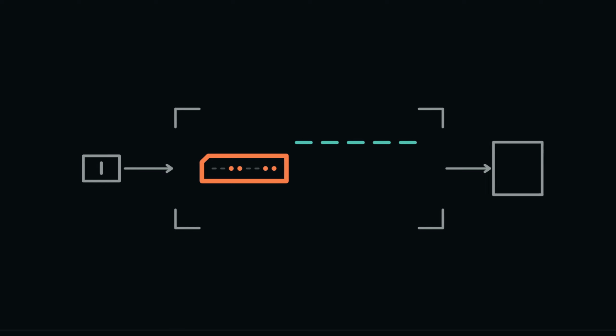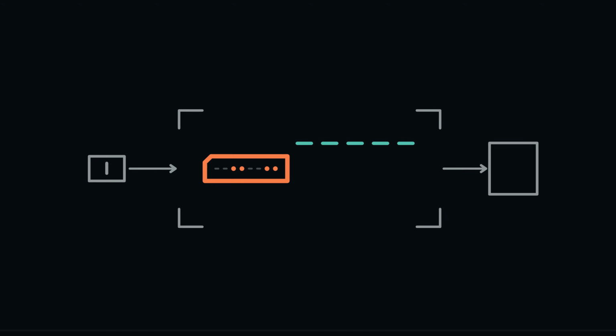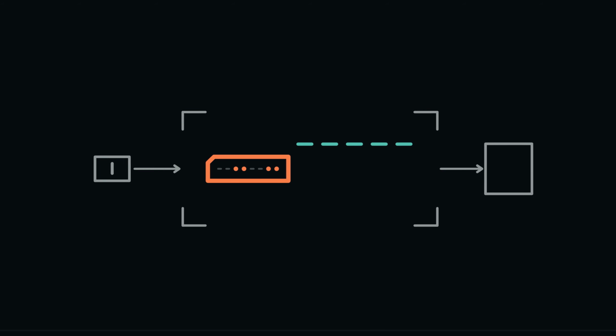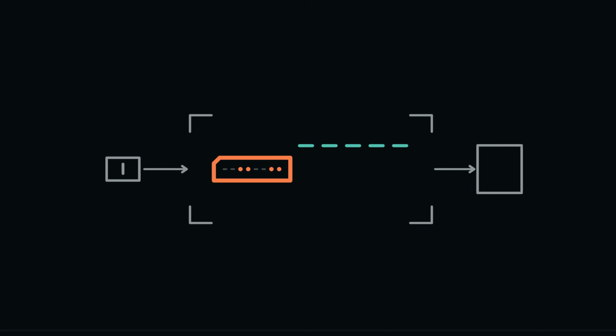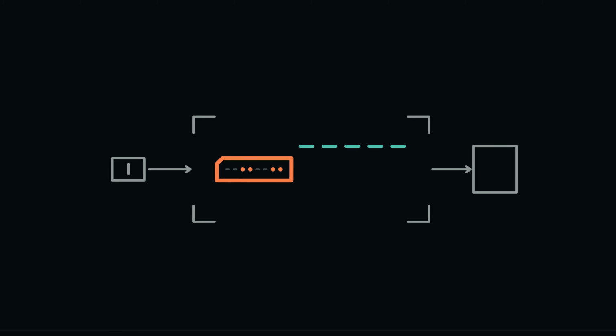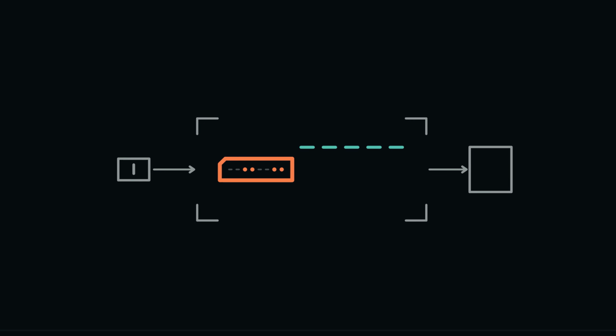Binary addition keeps that relation but replaces 10 possible digits with 2. The comparison maps place to bit position and carry to a 1 passed toward the next larger weight. It stops there. No person is writing intermediate marks inside the circuit. Proven gates establish output signals according to the same arithmetic relation. We will build one column, test every case, then join 8 copies without hiding the carries between them.